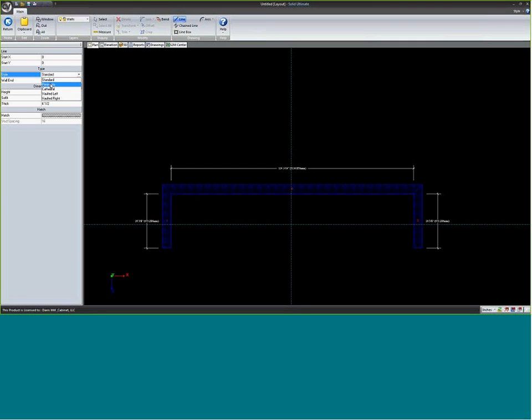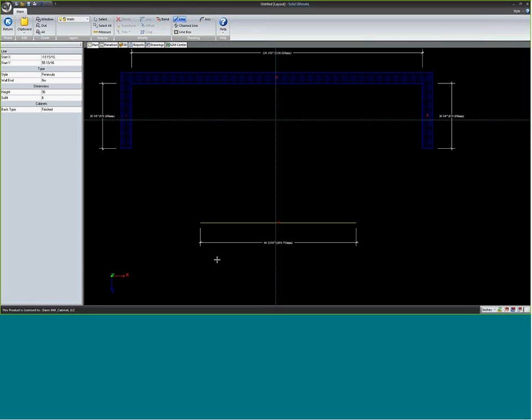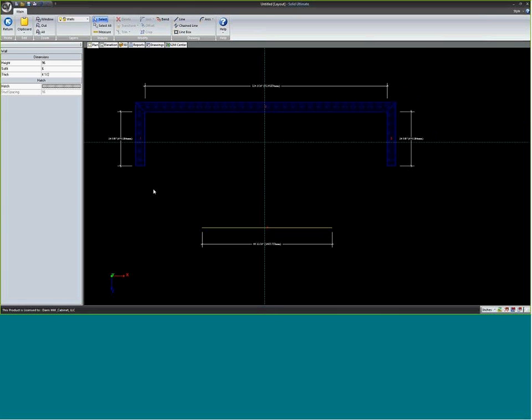So peninsula wall is a little confusing to people, though. If you pick a peninsula wall, notice the standard walls I've drawn have thickness to them, whatever I've set my standard wall thickness to be. If I draw a peninsula wall out here, again, I want to draw from this island I'm drawing here, so I'm going to have cabinets on this side of the island. So I want to start on the width of the island if I'm looking at the face and drag to the right, the wall's up down. So notice that this peninsula wall is yellow and it has zero thickness to it.